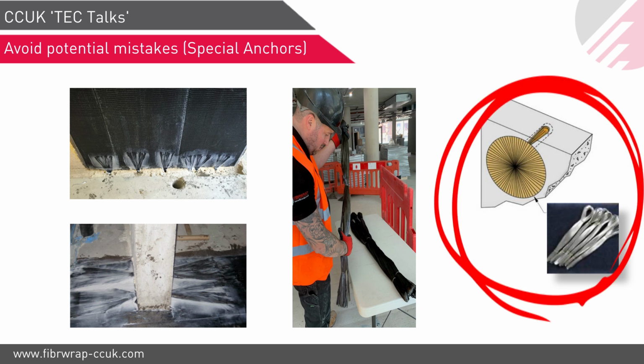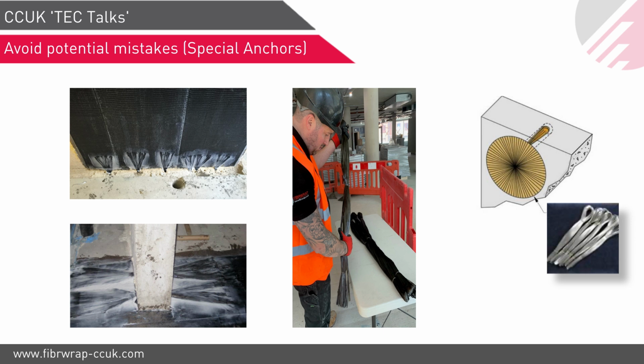It is, yeah. And then we put one more layer on top of it, so it will become one unit which will cure simultaneously, but it is actually going into the concrete. So it provides you additional anchorage or bond capacity, so your debonding or delamination failure will not happen. These kind of smaller nominal anchors are used mainly for construction detailing or for shear strengthening.